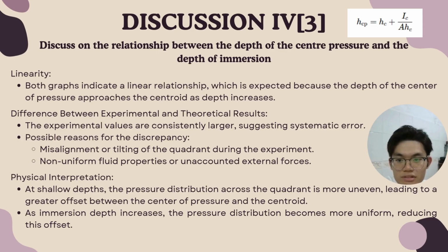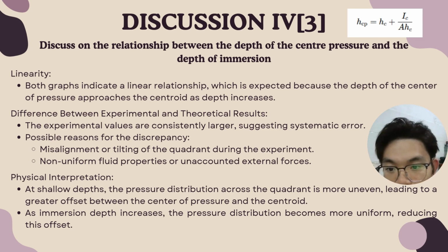Okay, discussion 4 is to discuss the relationship between the depth of the center of pressure and the depth of immersion. The equation h_cp equals h_c plus I_c over A h_c shows that the relationship between the depth of center of pressure and the depth of immersion is linear. Both parts indicate a linear relationship, which is expected because the depth of the center of pressure approaches the centroid as depth increases.